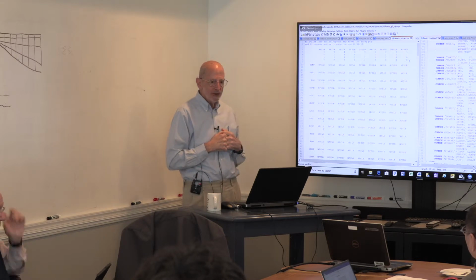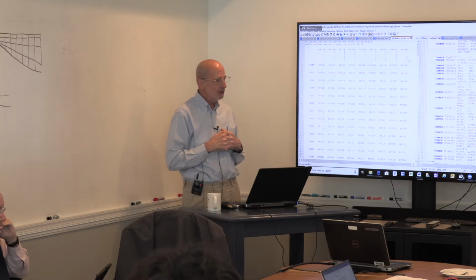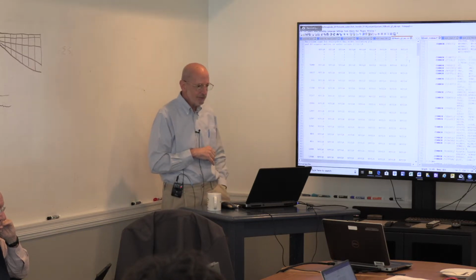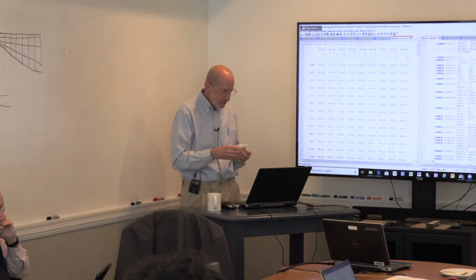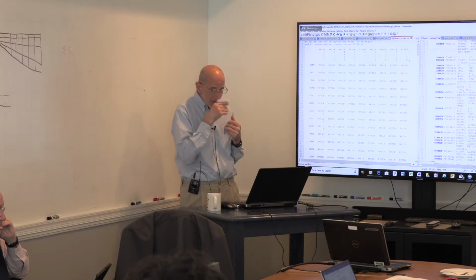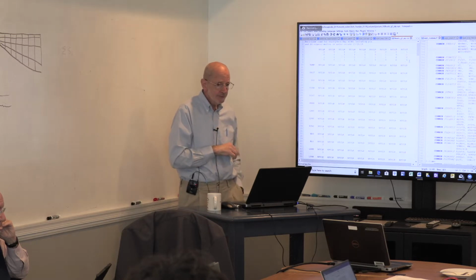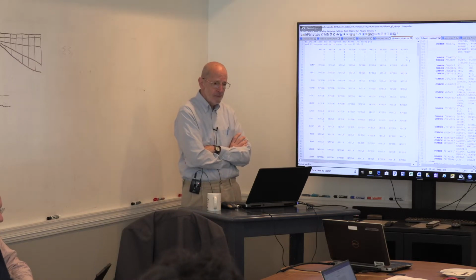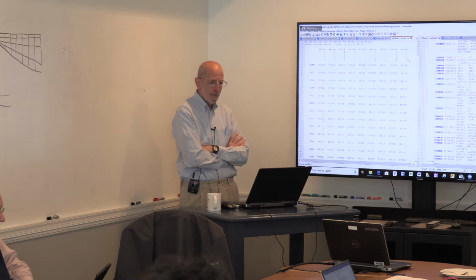The temperature equation, in a sense, is the same argument you're going to use for pathogens. It's going to be the concentration units, irrespective of whatever they really are. We say it's kilograms, but you basically just take your flow times whatever your concentration is, of either temperature or whatever. What about salinity? Is it going to multiply the salinity in parts per thousand, not convert the concentration? Well, suppose you had some place, let's say a desal plant. Then you would take your salinity in parts per thousand, because that's the unit salinity is in, and multiply by your flow. Okay.